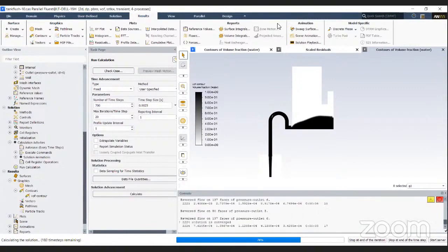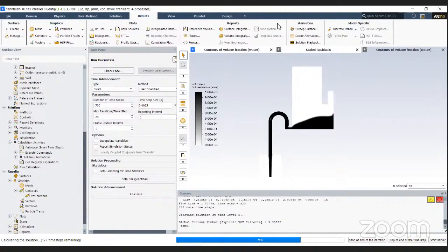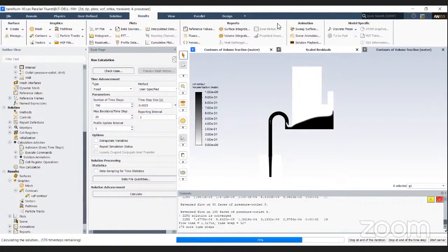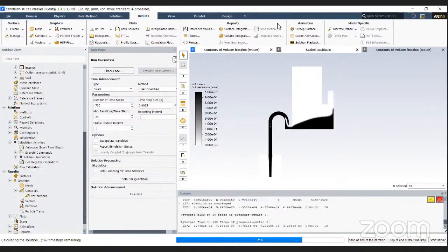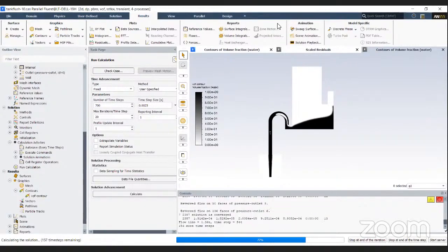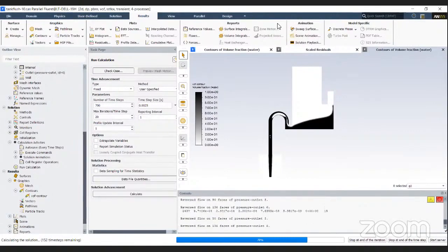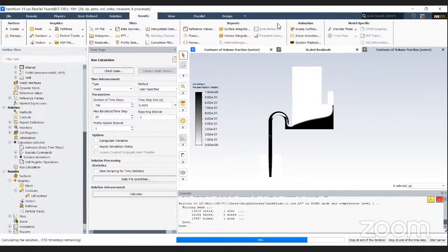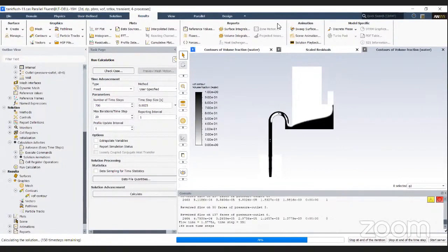But for those small bubbles, if your computational grid is sized such that it can capture the interface, then you can do both things with the same model, if that makes sense. But of course, with individual applications, it can get a little complicated depending on what you're trying to do, and that would require a little bit more investigation. But sometimes your mixture model, your VOF model, is multi-purpose, and you can use it to capture different types of phenomena in the same mixture.